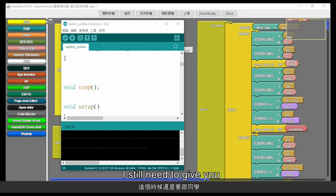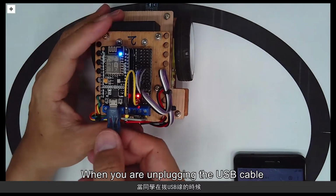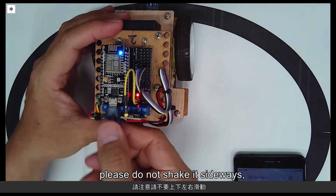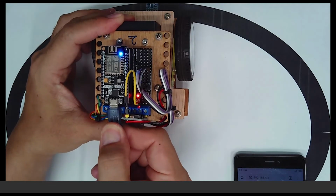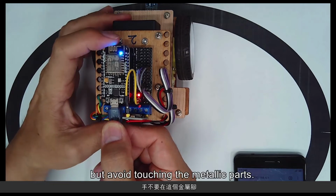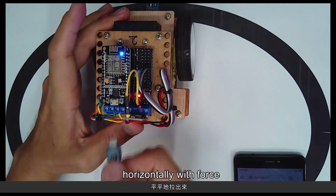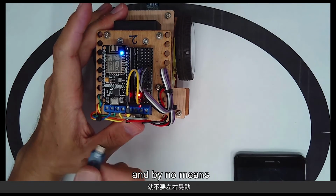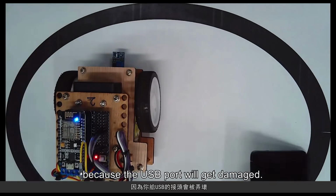I still need to give you a small reminder here. When you're unplugging the USB cable, please do not shake it sideways. Even if it's hard to unplug, you can slightly press down on the board. But avoid touching the metallic part. Hold it down from here and pull out the plug horizontally with force. And by no means shake it side to side, because the USB port will get damaged.